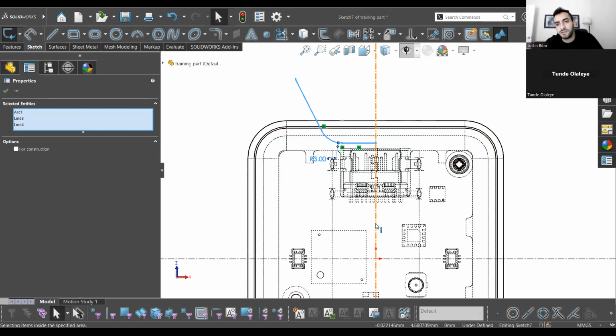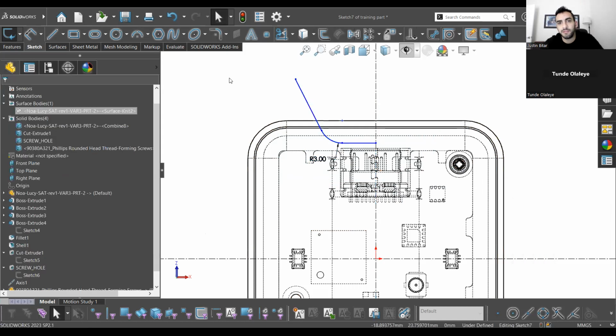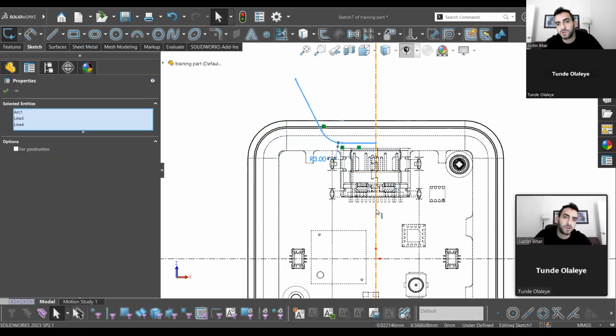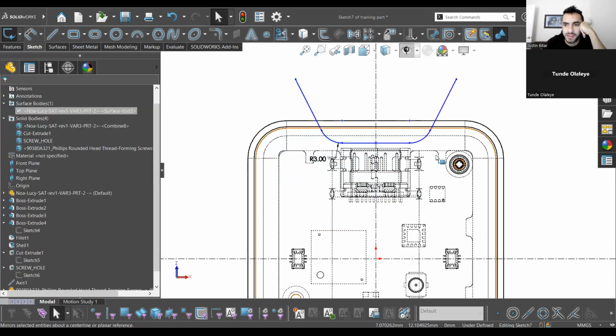I'm going to select all these lines, and then I'm going to control select this line. And if I do that properly, select this one, control select, and then I'll get this option here. And you may have to build out this menu too. Normal to is a really handy one. Don't do it right now. But mirror entities, I think that one comes default. So I can just quickly mirror these entities here. Okay, so I'm not even going to worry about enclosing this sketch.